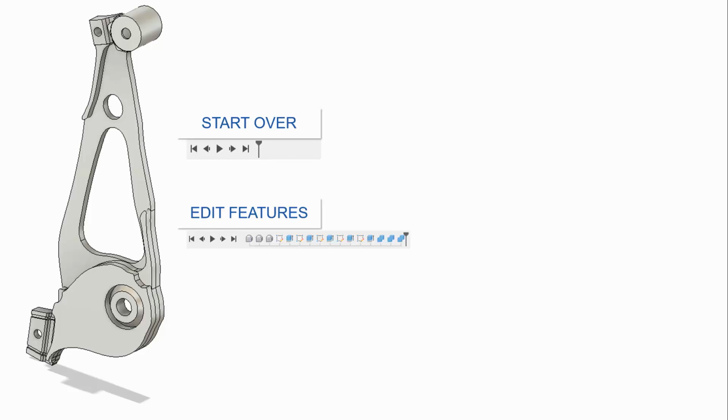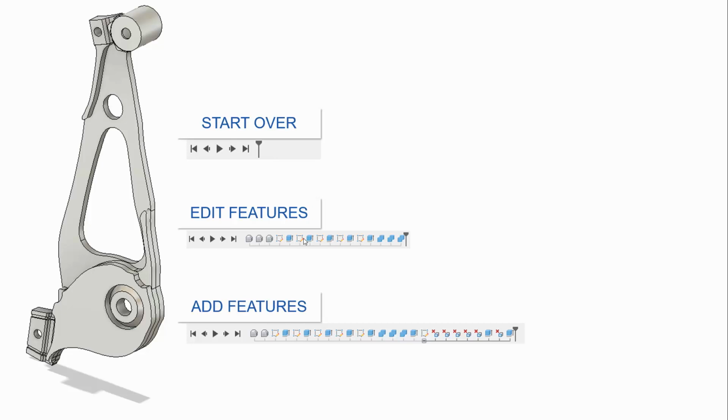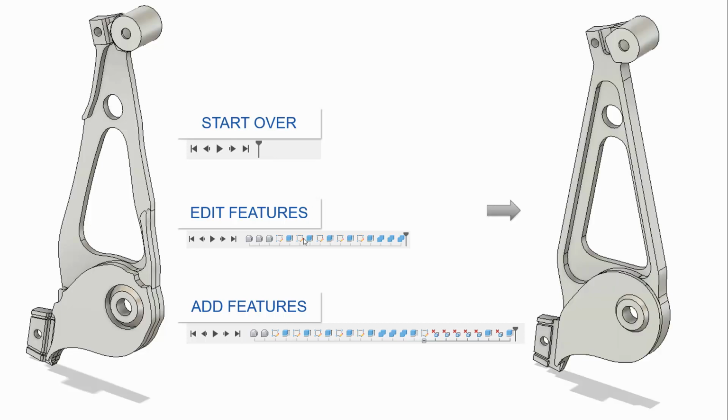Alternately, because this is a full parametric geometry, we could edit the features. We could take what's already there, the sketches and extrudes, and modify the sketch geometry to fit our own purposes. Finally, a third way of approaching this is to keep what we have, but because it's an intelligent solid, a first-class geometry, we can go on from there and add new features to the timeline, add new extrudes, delete faces, rearrange things till we get the behavior that we want.